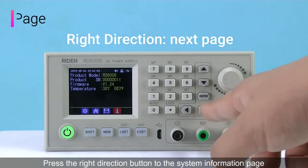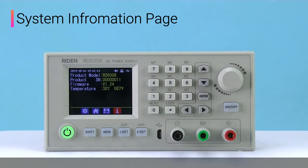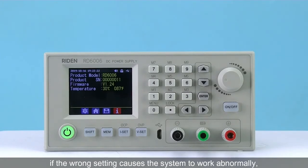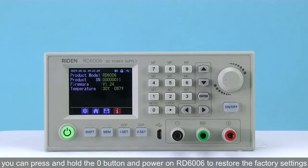Press the right direction button to the system information page. You can check the serial number, firmware version, and the system temperature here. If the wrong setting causes the system to work abnormally, you can press and hold the 0 button and power on RD6006 to restore the factory settings.